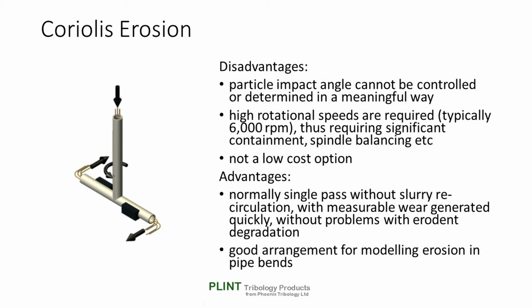The advantage of this type of rig is that these devices are normally single pass without slurry recirculation, with measurable wear generated quickly without problems with erodent degradation. And it's also a good arrangement for modelling erosion in pipe bends.